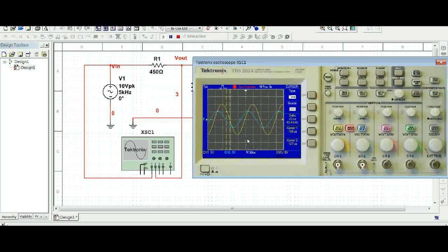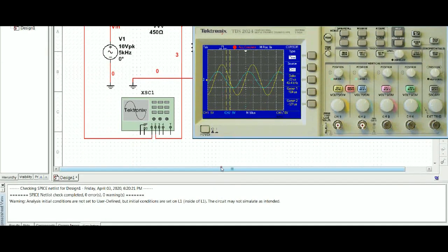Now the frequency is 500 hertz, and the period, capital T, is 1 over the frequency, which gives us 200 microseconds. So the calculation looks like 23 microseconds divided by 200 microseconds will give us the ratio. The unit of microseconds divides out. We're going to multiply that by 360 degrees. I'm going to do it on a calculator here.